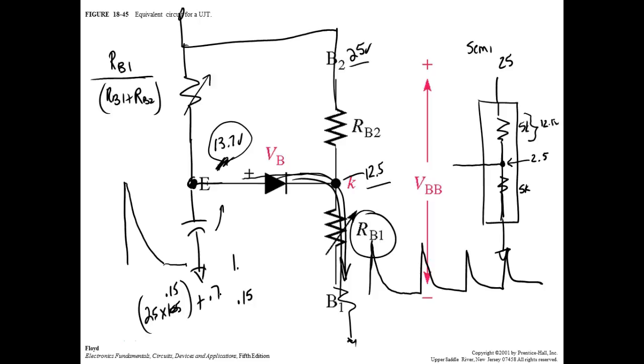So there's no way in the world. Both of these require the negative to be connected to common. The only one I've got connected to common is this right here. I can't do that. So what you're going to have to do is use one of these power supplies in the lab. Okay. Now remember, you're going to have to look at the common. You can use another thing.